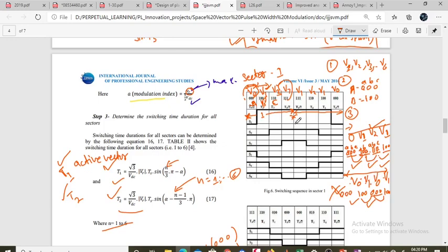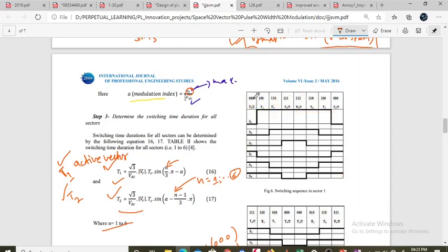So according to that you can make your own switching sequence. It is not necessary to just follow this conventional rule, but you can choose your desirable switching sequence, where you find that this switching sequence will provide you less switching losses. And obviously this is one of the good points for research and for project making purposes. The research papers will provide you better information about that. So the switching pulse response for each subcycle is shown.